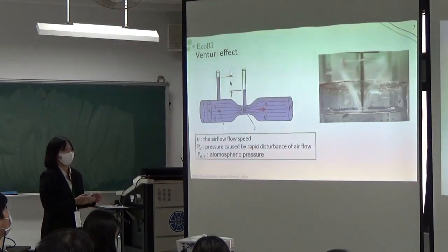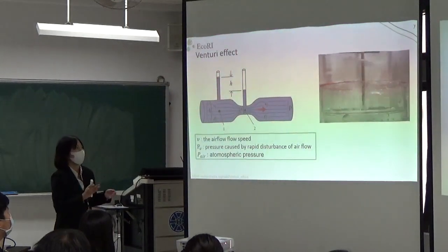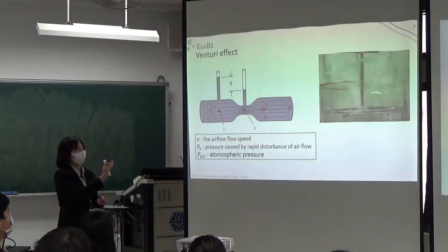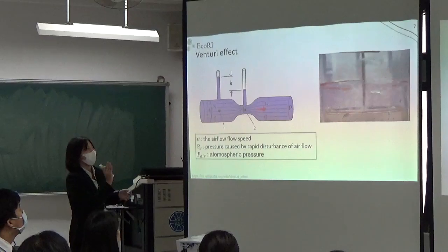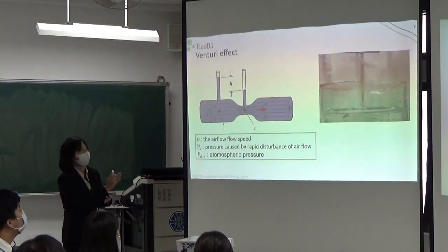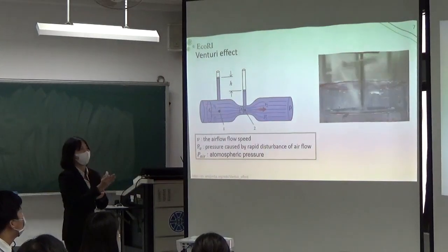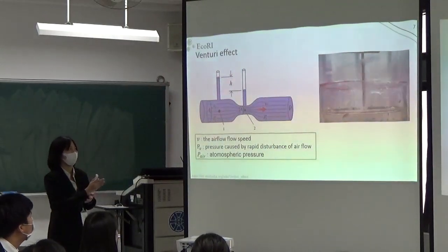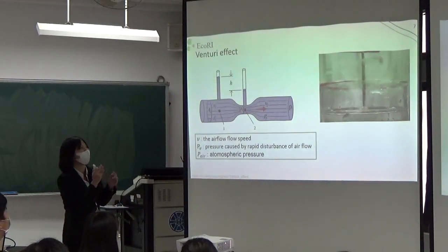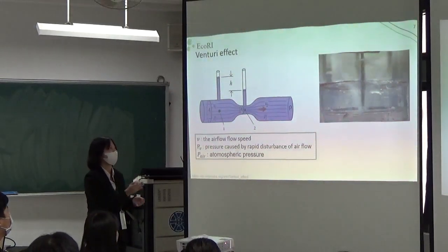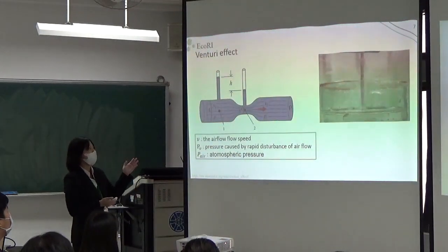And here is the extra observation. The right side video shows that when the water level is lower than the straw's inlet part, the straw can also pump out the water. But the process is not continuous. The straw will rotate without pumping out water for a short time, and then suddenly pump out a little bit of water, and then come back to rotating without pumping water. And we think that is because of the Venturi effect.